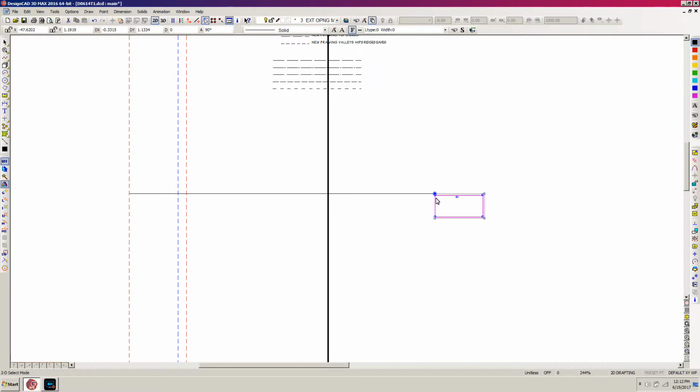So now I'm going to move that door over to the left, M, move, get over to that area, close to it, and then right click, and it snaps the door to that point. And now I hit escape, and it's unselected, and there it is. And now I can right click on this line and delete it.